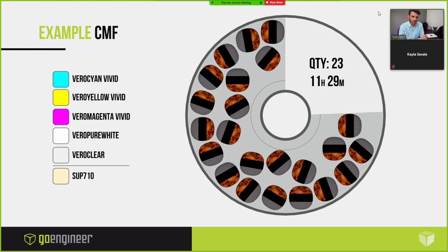I did mention that there's 5 core materials that you would load up on the machine. In reality, there's 6. One is a support material. That support material is there to allow you to build unlimitedly complex geometry. Overhangs, undercuts, that sort of thing. That support material is washed away with an electric pressure washer.